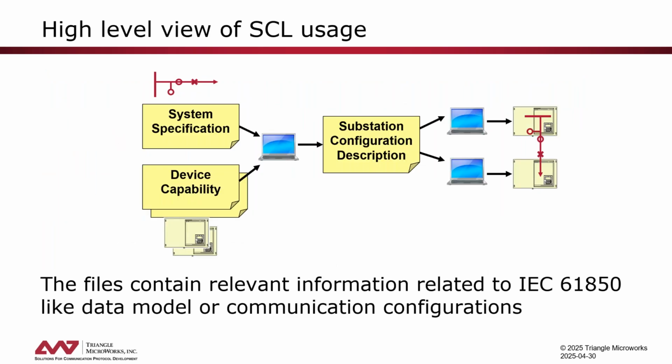In part 1, Jackson has introduced this high-level view of how we use the system configuration language with the different files from specification, describing an IED, the system tool that builds the system and creates the complete file with all the configuration that is then used by the IED tools to download in the devices. We will not focus much on this engineering process today. For that, we have our own dedicated webinar in the future, but we want to introduce basically how an IED is represented in that SCL model.